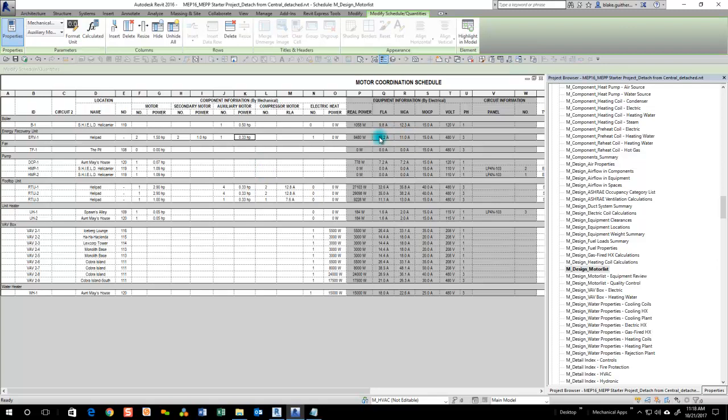So we're calculating all of these for electrical all the way to the point of that apparent load at that connector just by doing our own part and filling in our own information. Now say we also have electric preheat like our cut sheet indicated, and say we have a 15 kW heater in this, and now you'll see, magically all these values update.